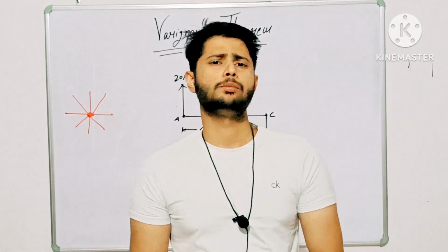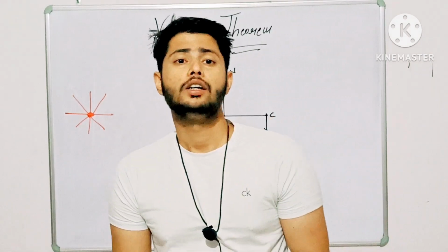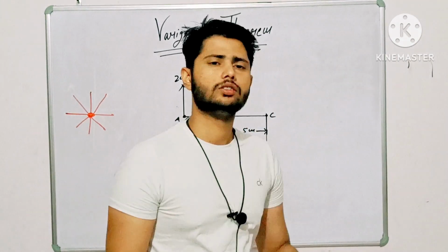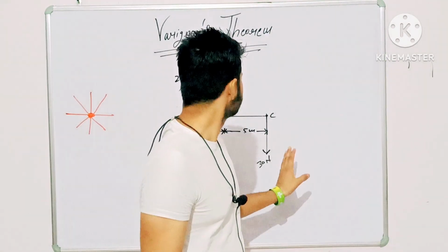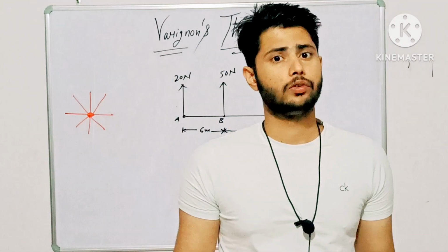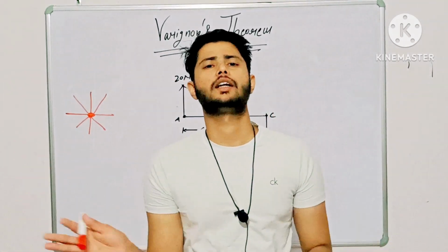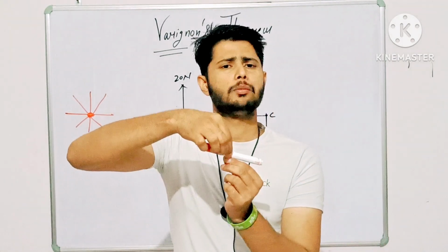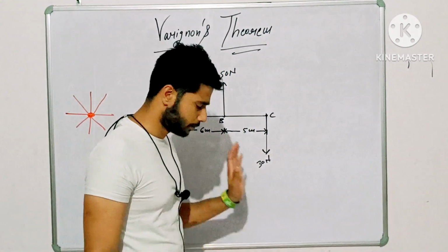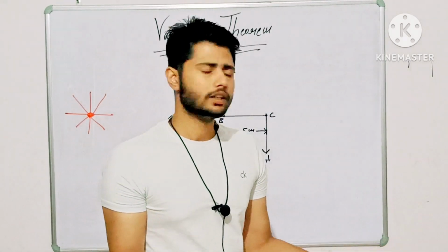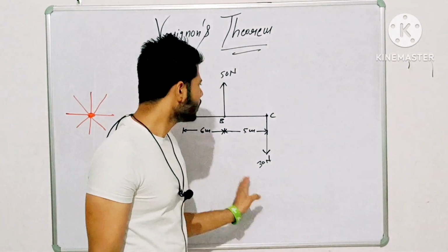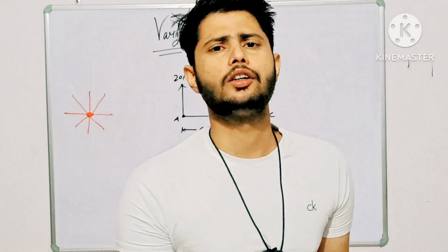According to Newton's second law of motion, the body will move in the direction of the resultant force. Horizontal force is not available here, so the direction of your resultant will be vertical. This body can move in the upward direction or in the downward direction, but it cannot move in the horizontal direction because horizontal force is not available here. So according to this figure, we can easily find the resultant by the summation of vertical forces.